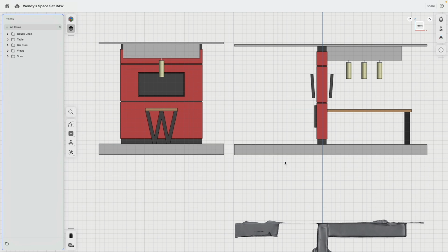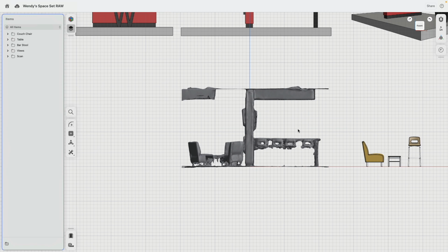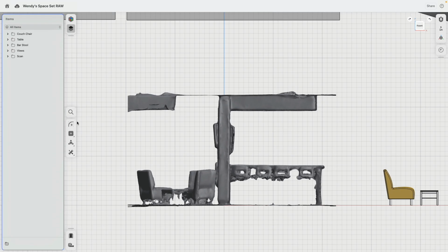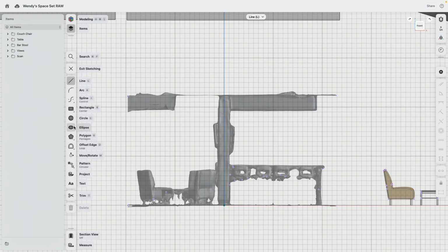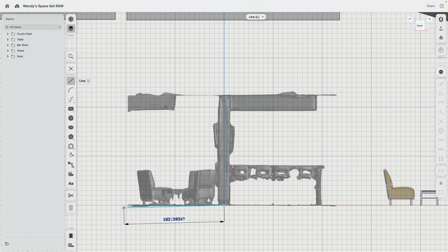We can see that essentially we can draw everything from the side and then extrude it out left and right. I could also do the same in the front view, for example. But here drawing this wooden board will actually be easier because I can just left and right define where that is. So that's the reason why I'm going to start sketching this here. I start with a sketch from the origin. I go over and down and back and up and to the origin again and escape.